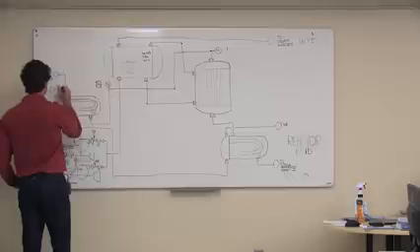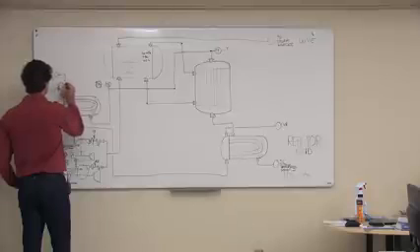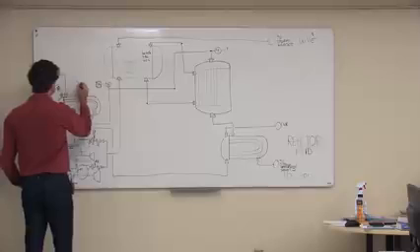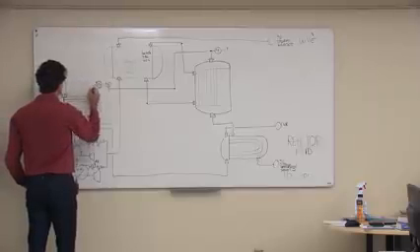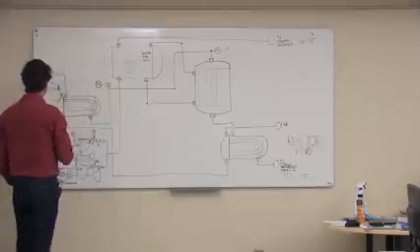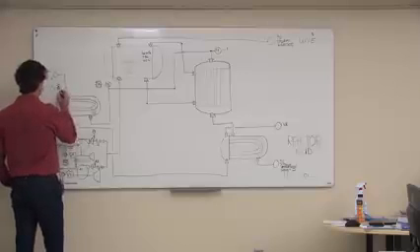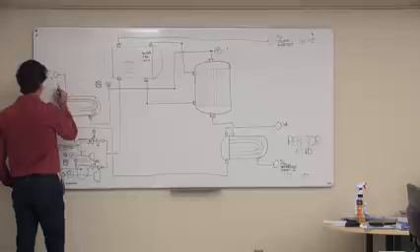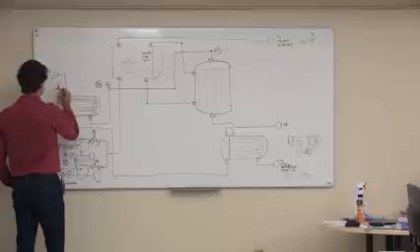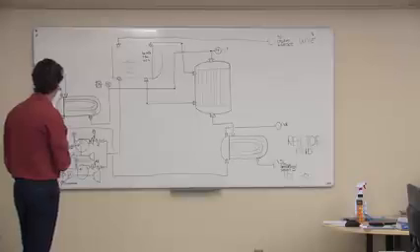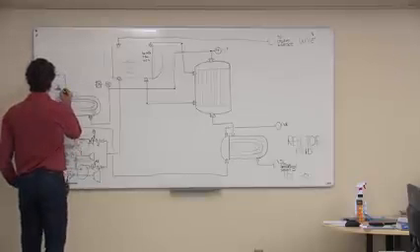Right there. Let's fail it open, because cooling the system off is probably a good idea in the event of a failure. Like that. And most of the control valves are a line size smaller than the actual pipe. So it's generally a safe assumption that you're going to need a pipe reducer on the inlet and the outlet of the control valve. It may not be the case, but you might as well throw it in there because it's probably going to end up that way.